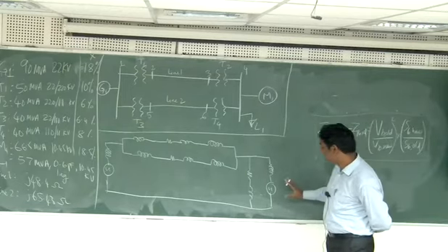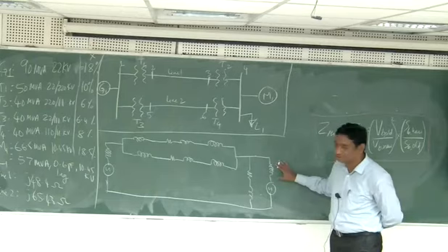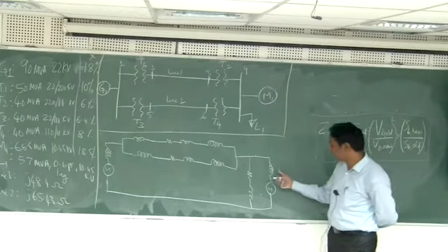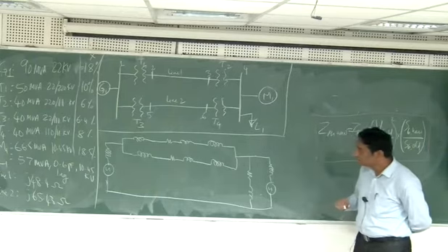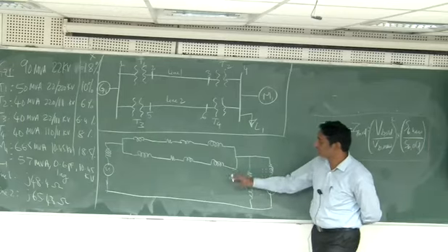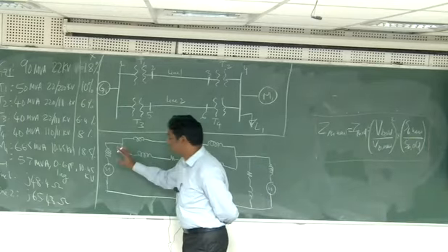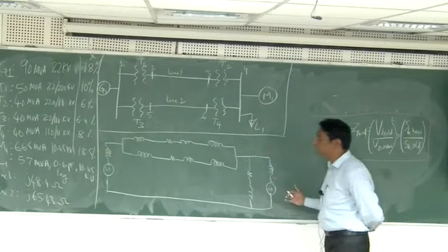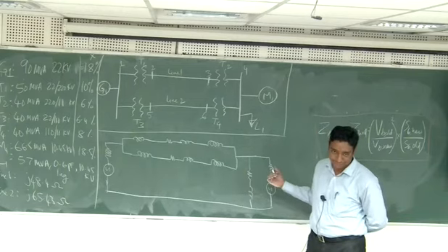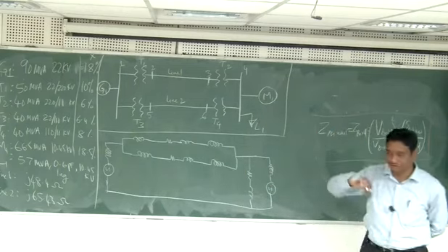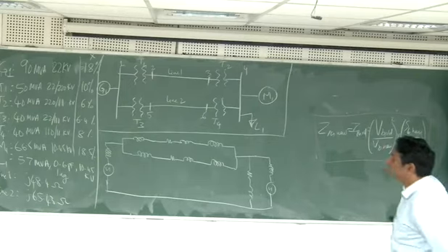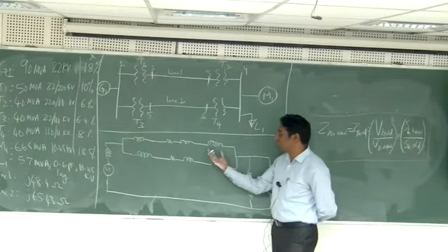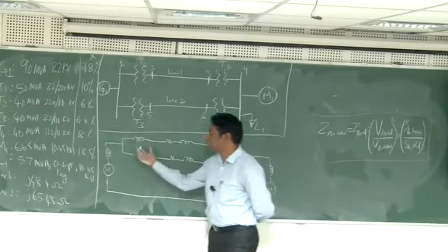So you can model the motor in the form of a voltage source with a reactance. All these things we have to put some numbers. If you put some numbers, then it is easy to solve this circuit, whereas this circuit is difficult to solve. There are no transformers here; the transformer is replaced by a simple reactance.